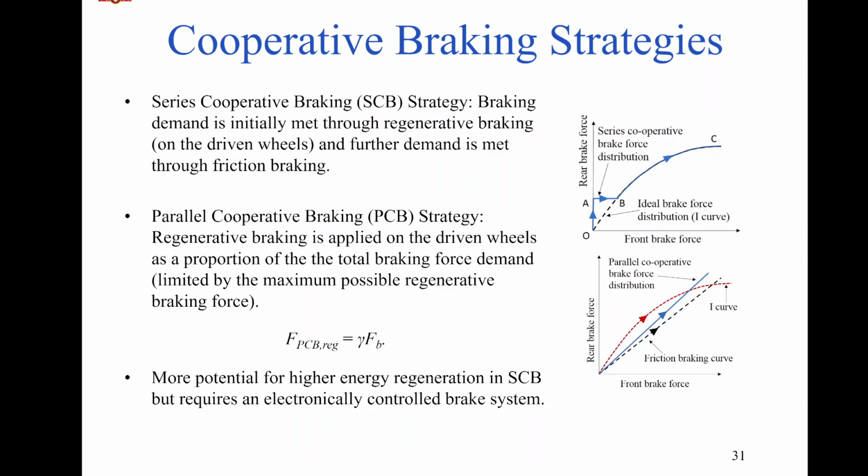So the first choice would be regenerative braking, in the sense that you will get maximum energy back. But if your demand is not getting fulfilled by regenerative alone, then we need to bring in friction as well.